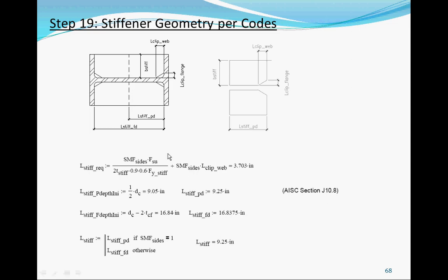For our connection, our FU is typically a lot less than your beam flange, because you're taking the whole flange to calculate FU. We're just taking the reduced one. We're using FU instead of FY, but typically ours is a lot less compared to the other connections. This one most likely will govern because of half the column depth. So you can see the difference here is quite a bit.